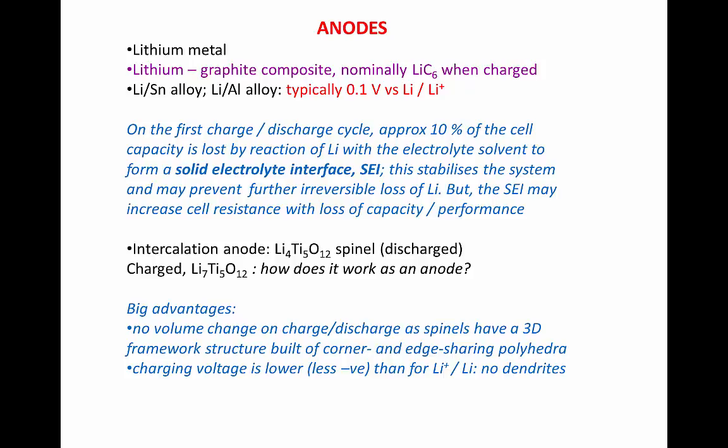It stabilizes lithium in contact with the electrolyte. And of course, that is vital to long-term stability and performance of your battery. You don't want the components reacting irreversibly with each other. So formation of the solid electrolyte interface is good news because it stabilizes the system, but it is bad news because a certain amount of the lithium is lost from the system by reacting with the organic component of the electrolyte.